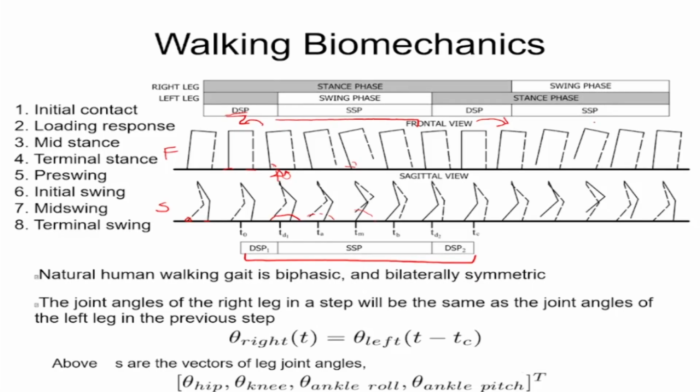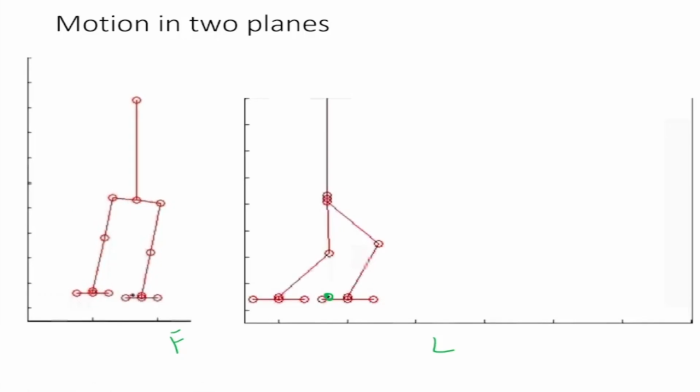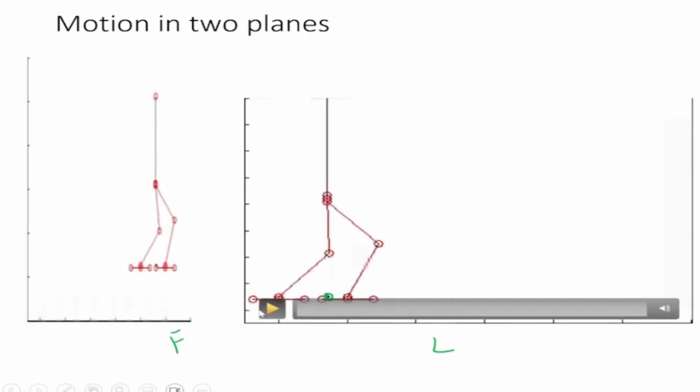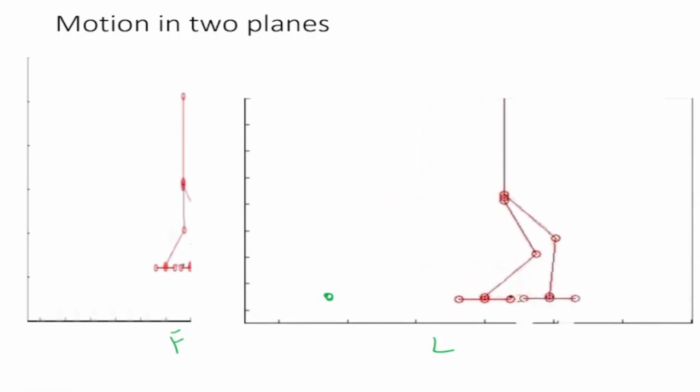Now what we are seeing is that the robot has to move. This is the video I had shown in the last class also, I think, in which we have the frontal view, and you can see it is bent on the left side. It is just moving from one side to another side, going through single support, double support, single support, double support. This one is the side view or the lateral view, you can see that the rear leg is moving forward and becoming the front leg, and the body is also moving forward.